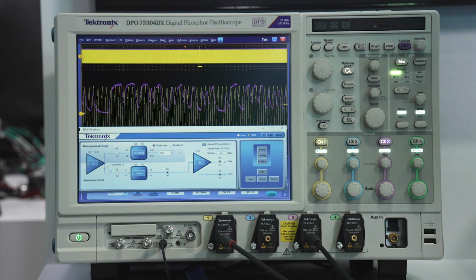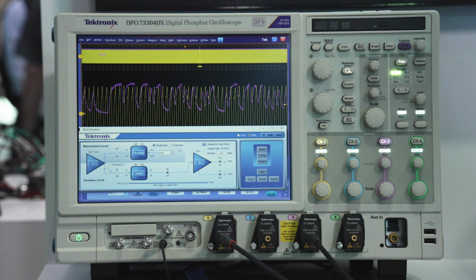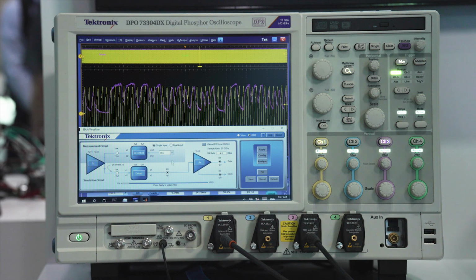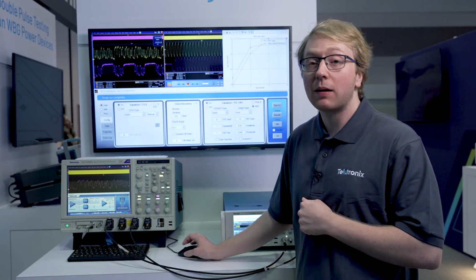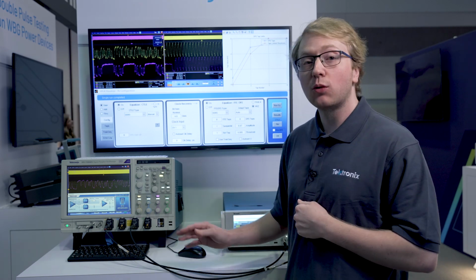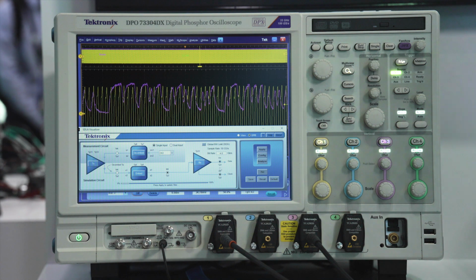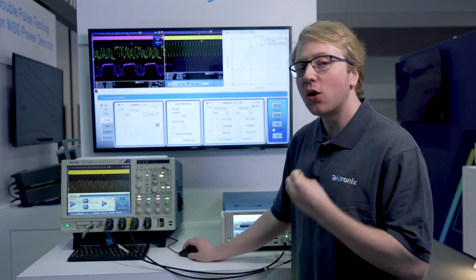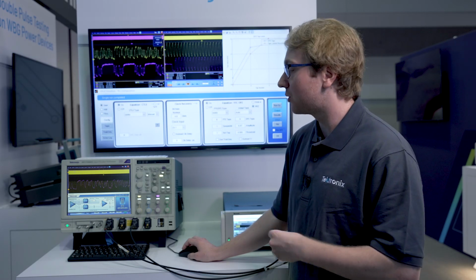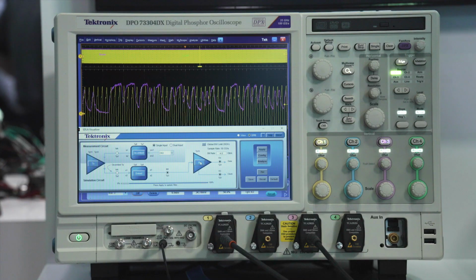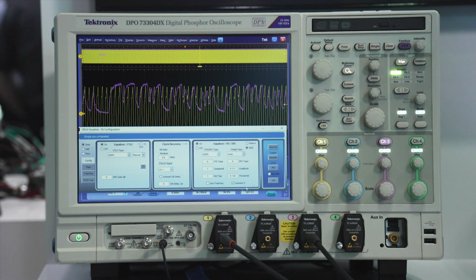Just for some quick context, I have my channel 3 here, which is that purple trace, as my data input into this system, and it's going to go all the way around. These radio button styles here are where I'm selecting to move my virtual probing point. We have a capability now where you can see I have these points selected after the receiver, which means I'm going to have data that is post-equalized after the DFE, which is a really powerful capability. If I go into that receiver block, this is where we're actually setting that up.